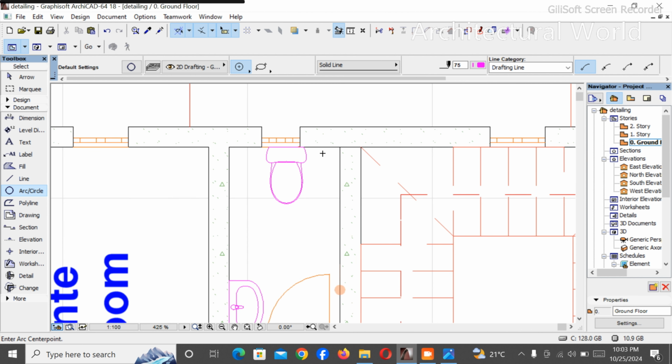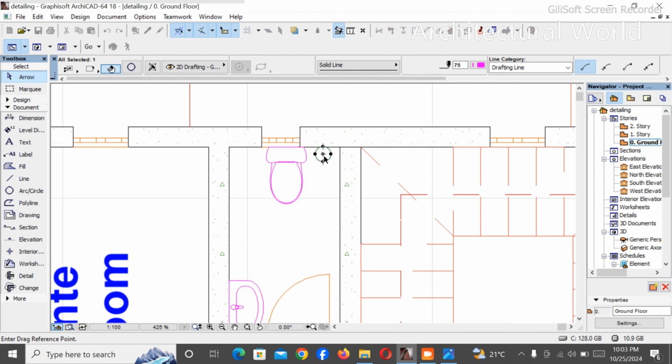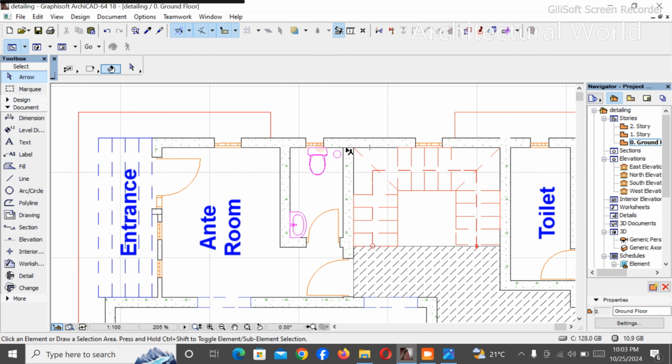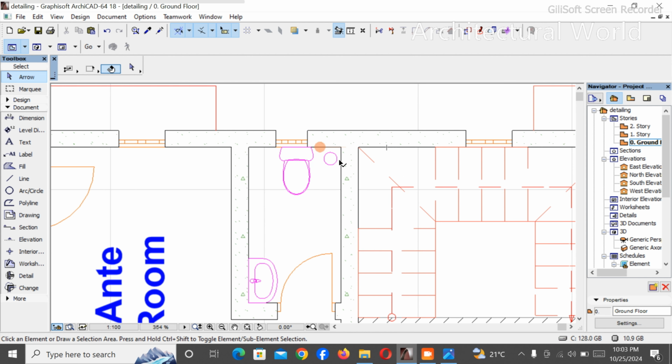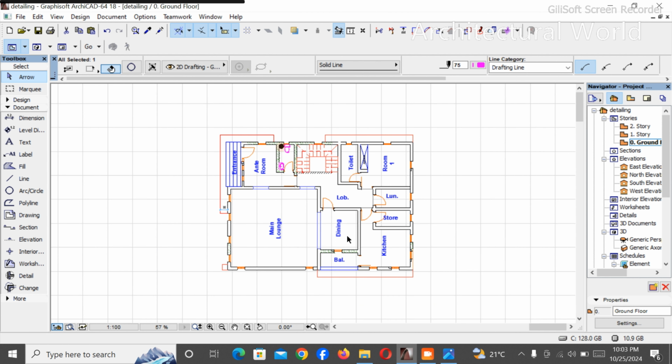You can put your floor drain here. Now this is floor drain. Let me show you. You can put it either here or here. Any of these sides is okay. This is your floor drain. But if you put your floor drain here, you'll be having excessive waste of pipe. But if you want to save consumption of material, you can put your floor drain here. I'm going to show you why when I'm doing the detailing.